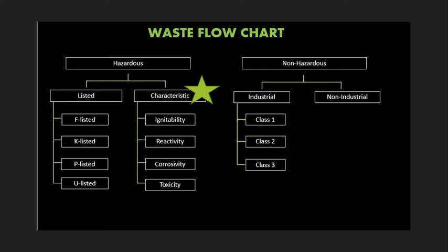The next portion of hazardous waste that we deal with more on a routine basis is the characteristic hazardous waste. So this is stuff that everybody's familiar with. Ignitable waste, so it's got a low flash point. Reactive waste, it can release fumes and off gas and all sorts of things if it's in contact with water. So there's various different examples for that. Corrosivity, so if it's corrosive, if it's an acid or base, and toxicity. So that's heavy metals like lead. We'll run through some more examples.